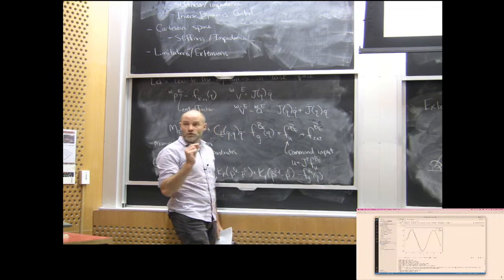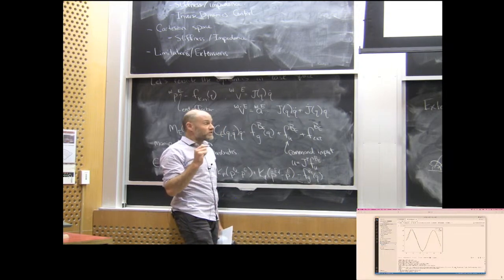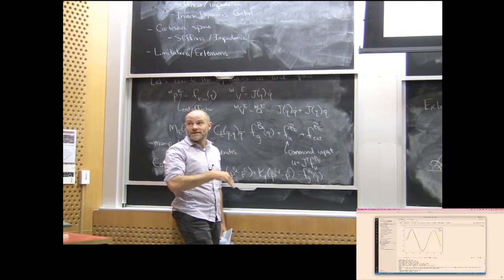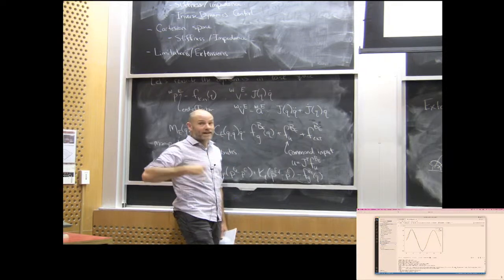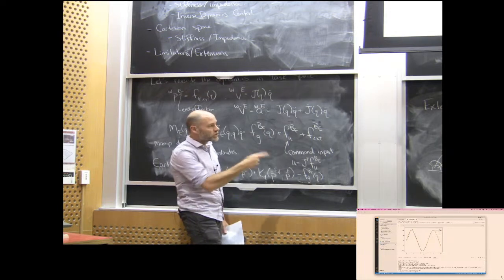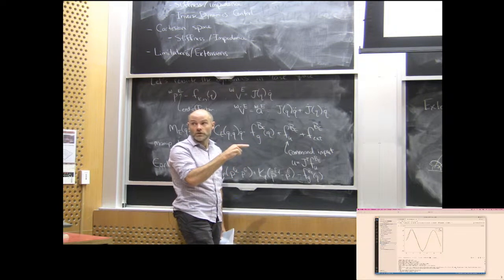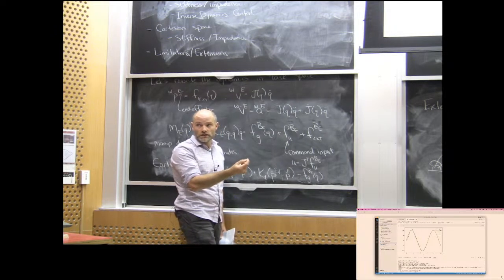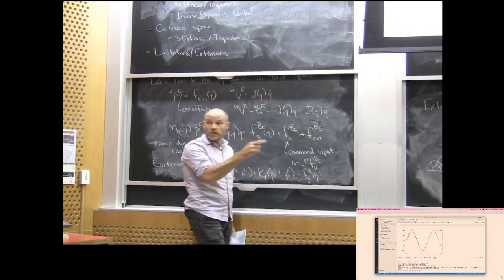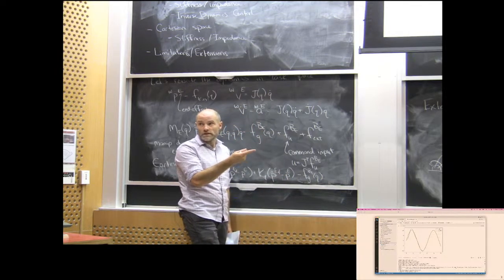So yes, in the limit, you could set Kp and Kd in the joint space impedance controller to 0. You can say, I know everything I should know. It will still compensate the gravity torque for you, and it actually does a little bit more. It compensates friction, too, in a very clever way. But then you can command forces directly to add in.